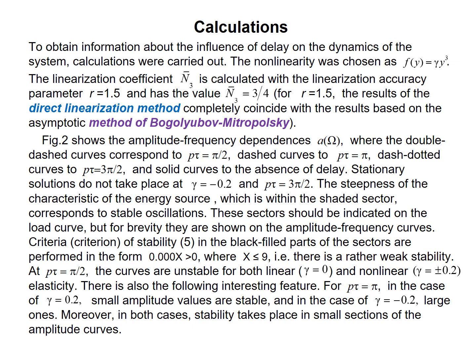Figure 2 shows the amplitude-frequency dependencies, where the double-dashed curves correspond to one delay value, dash-dotted curves to another, and solid curves to the absence of delay. Stationary solutions do not take place at certain values, and the steepness of the characteristic of the energy source, which is within the shaded sector, corresponds to stable oscillations.